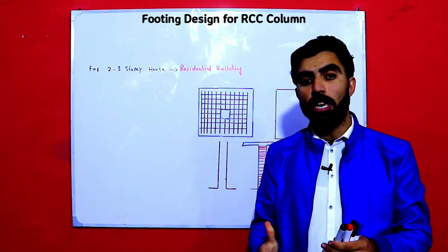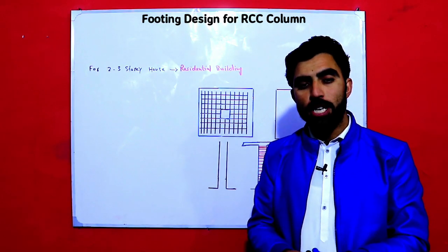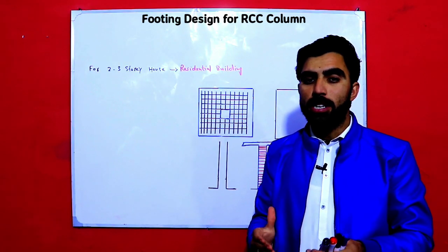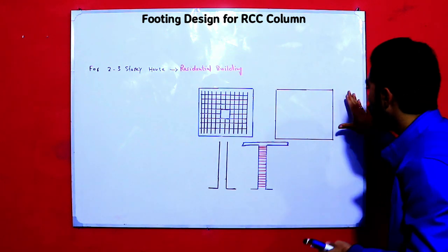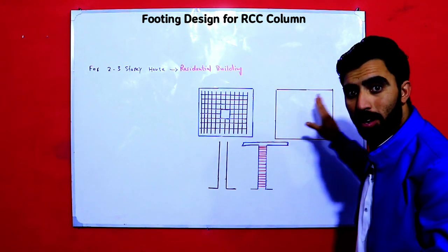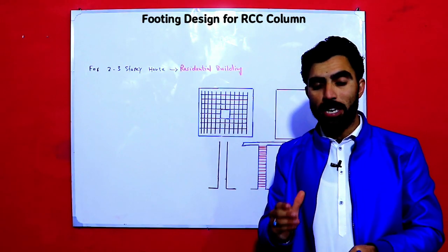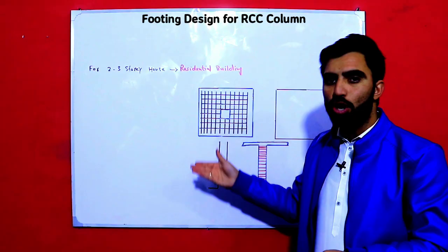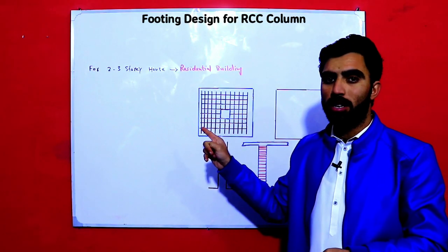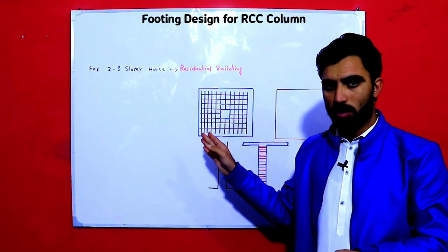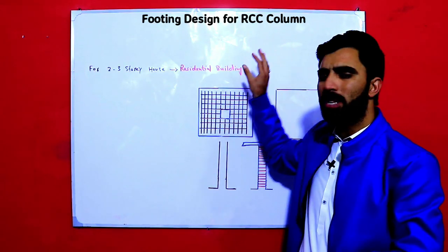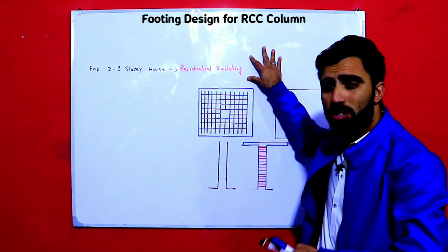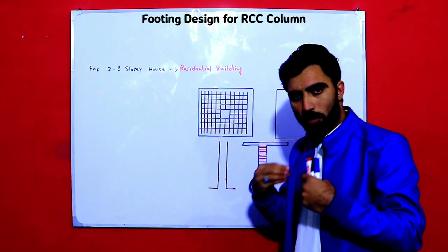And also SBC, soil bearing capacity, because we have different types of soil, and for different types of soil we can decide different sizes of footing. It also depends on the SBC, the soil bearing capacity of the soil on which you are constructing your project. So from that soil we will check its bearing capacity. There are some factors, but I have already discussed them. I will not discuss anything from the reference of any book, but I will give you information from my personal